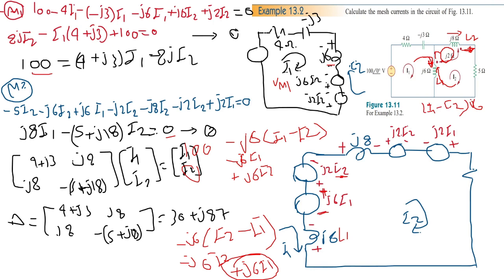And with the presence of j2 and having I2 passing through L2, this would generate a mutual inductance voltage around L1. Because of that, we have to check the polarity or the dot convention.